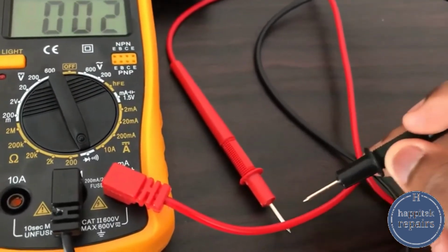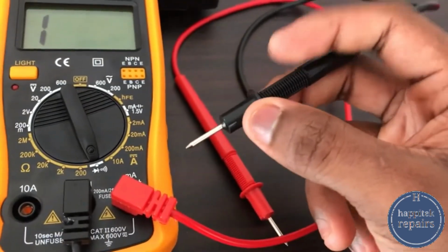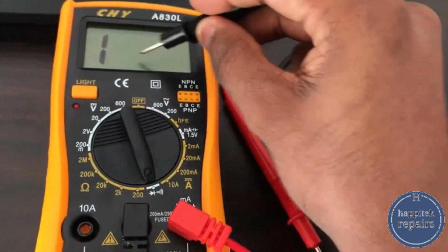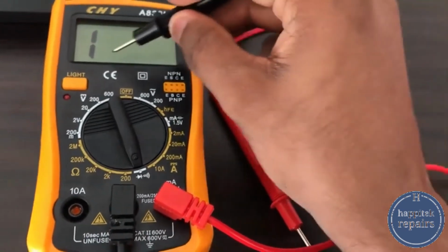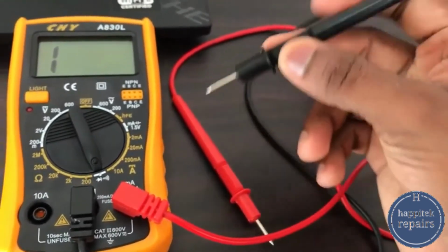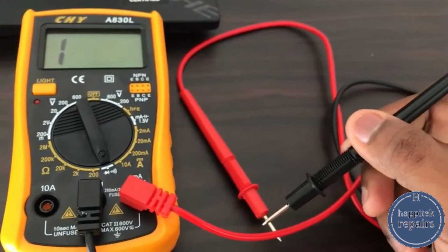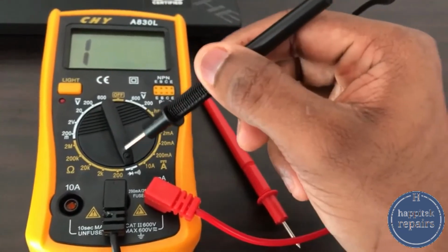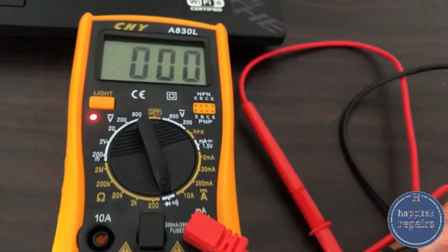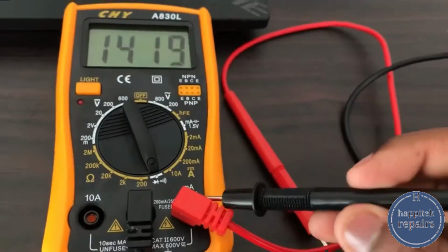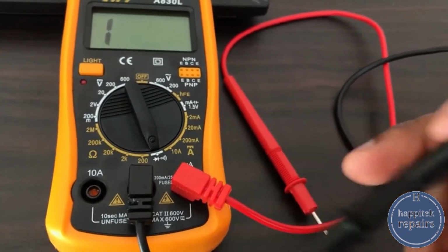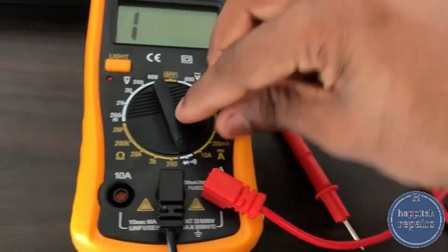If you want to measure continuity, or a forward bias, you can also use that range for a diode reading, forward and backward. You can use that range for continuity to measure a straight wire. Once it gives a sound with a light, that is continuity, the buzzer, and it will give a beeping sound.